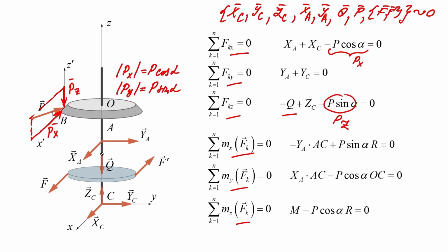The moment of force yc with respect to the axis x is equal to the product of the force magnitude and the distance from the force's line of action to the axis x. The moment is written with a negative sign because as we look towards the axis x, we can see that the force yc is tending to rotate the body clockwise.